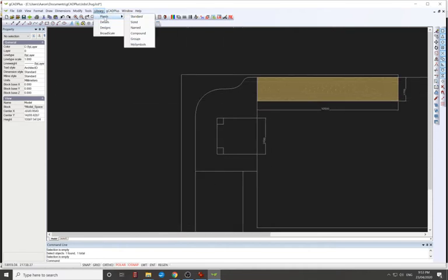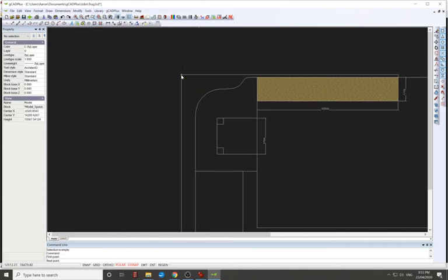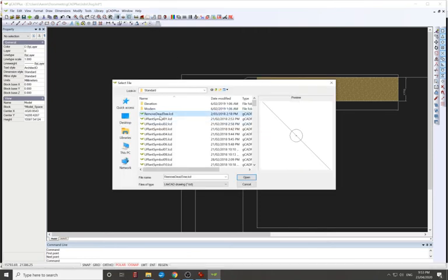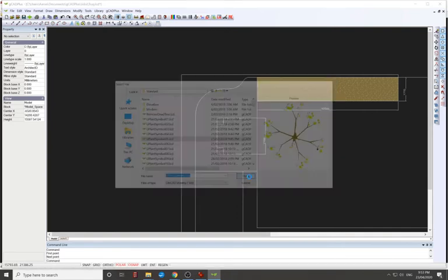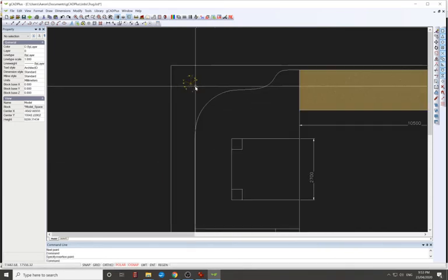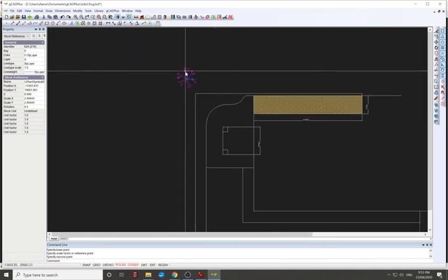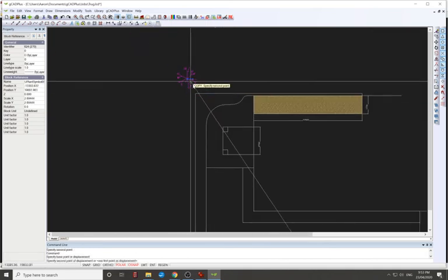The idea is, so what do we got here? We got library, tools, distance. We look at on the diagonal, what do we got there? 2 meters of space, 2.2 meters. Let's find a plant, standard one. Anything will do. These are just placeholders at the moment, so we'll open that, insert into the drawing. Okay, let's resize that. I'll just copy it from this point and just place it.